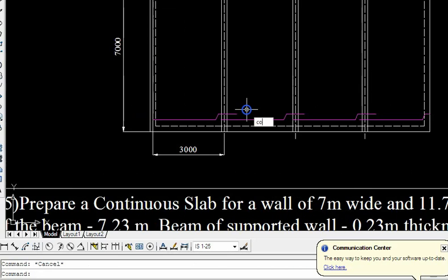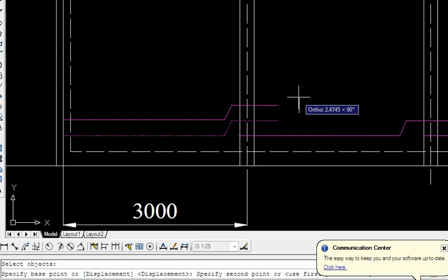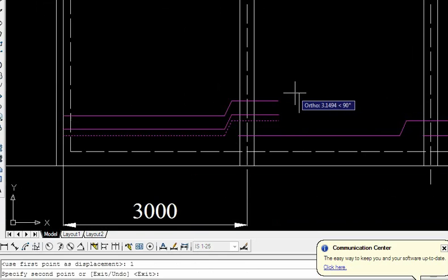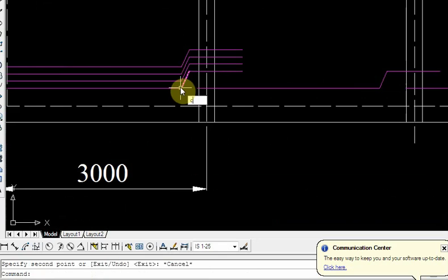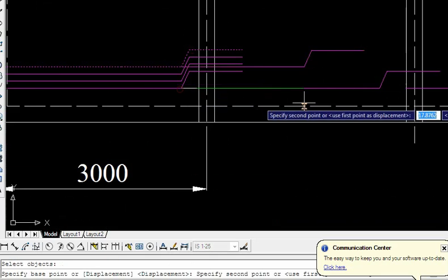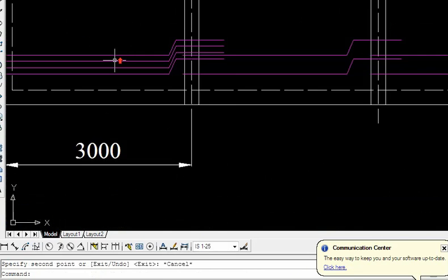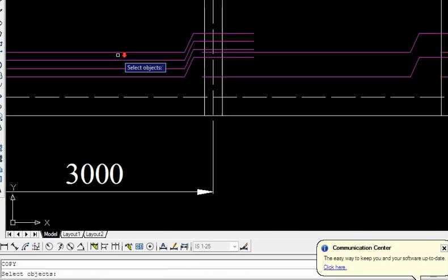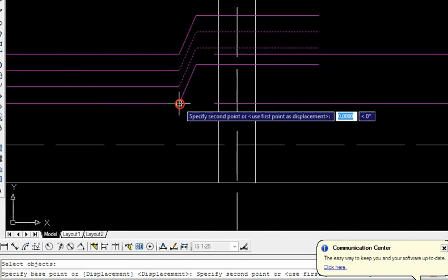Similarly, the spacing of this main bar is diameter 8 mm at 100. Every distance we are giving is 100, 100, 300. Yes, we can see it is bent like this at the edges. Copy. The third one will be continued for the second one, like this. And again at the edges we can see these two bars copied here.